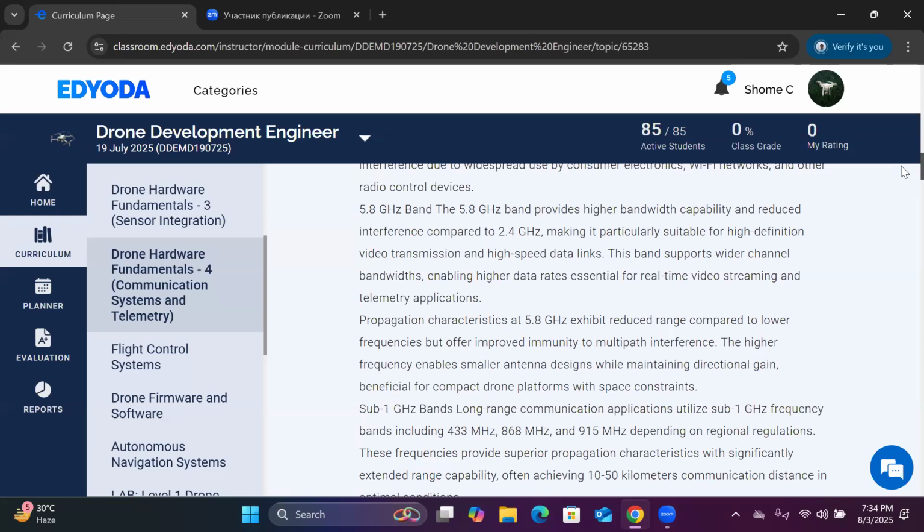Why isotropic? Because it will have the radiation pattern or the radiation intensity in all the directions the same. But for directional antenna, it is not the same. Directional antenna will have the radiation pattern particularly in one direction. So if we take an azimuthal plot, because for an antenna, if you go for a deeper dive into the technical aspects, there are a lot of parameters based on which an antenna is used, whether a directional antenna, an omnidirectional antenna, a helical antenna, a phased array antenna or a grid antenna, whatever type of antenna you use.